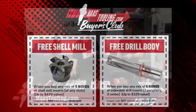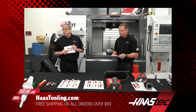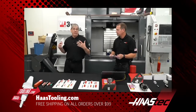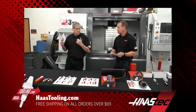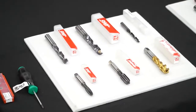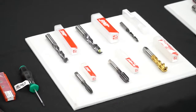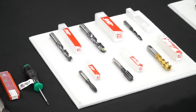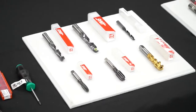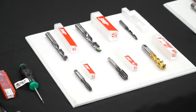So solid carbide drills here in the back, there's a couple of examples here. We have 29 different sizes available, including all of the tap drill sizes for inch size threads. We offer these drills in 2 different geometries. Both geometries are talon coated. That's titanium aluminum nitride coating, which is widely recognized as the best high temperature coating for drilling applications. So of the 2 geometries, one is for steel and cast iron. The other geometry is for stainless steel, high temperature alloys, and can actually be used on aluminum.